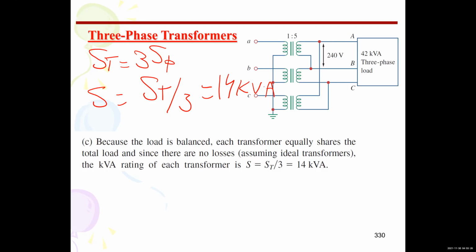Then we moved to the three-phase transformer. Three-phase transformer has 4 configurations: Y-Y, Y-delta, delta-delta, delta-Y. The only difference is if I have Y-delta or delta-Y, a square root of 3 will appear in terms of the voltage ratio or the current ratio in magnitude. All right. Of course, whatever we did with the wattmeter method also applies. Any question?